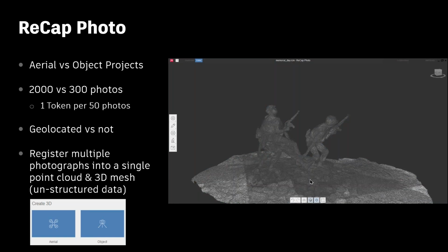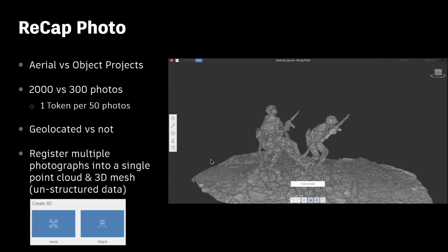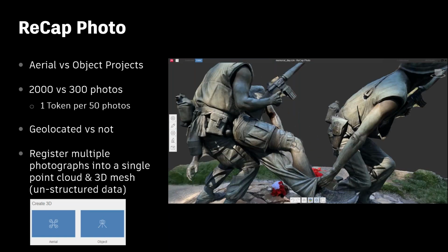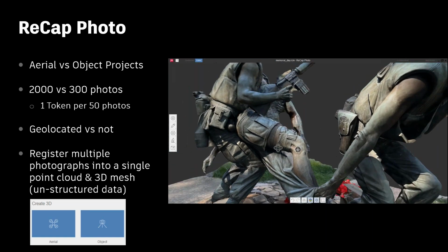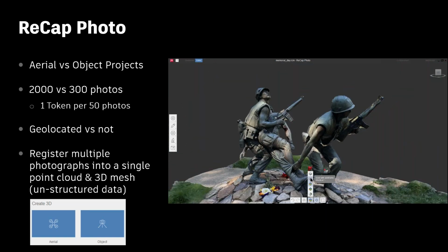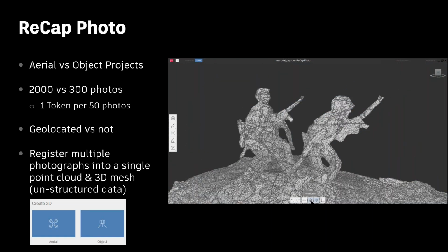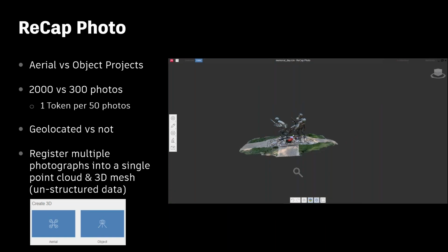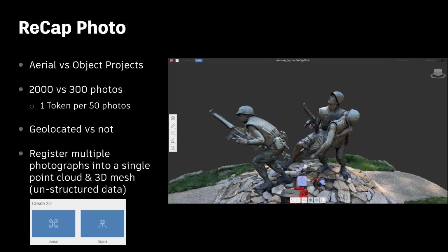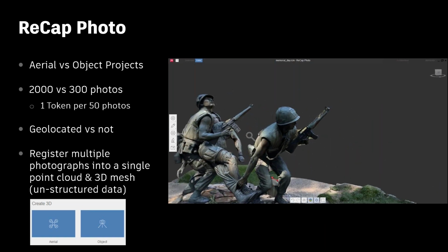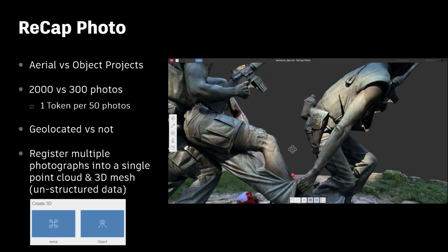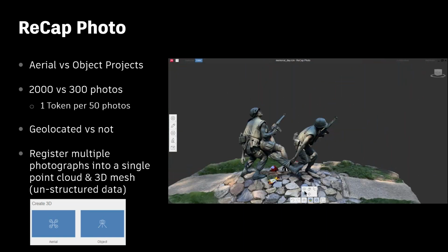It can be tied in using ground control points or just simply the GPS metadata inside of the photos from the drone capture. Keep in mind, if you rely strictly on the GPS data, it's not going to be as tight, as accurate. But in those instances where let's say you're going after a project, you don't want to sink a ton of time and money into that effort, that may be a perfectly acceptable solution.